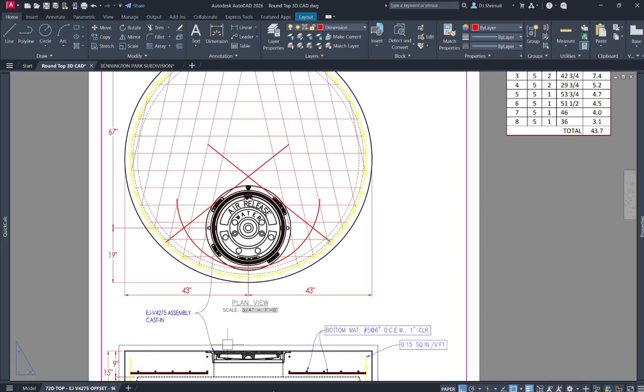Next, here we're going to need the tags for the length of rebars for each rebar that we need to cut, and then those tags we're going to put in the cut list table to create the complete table with the actual length of the rebar that the production guys need to cut to produce this top. They need to follow the drawing that we're going to provide.